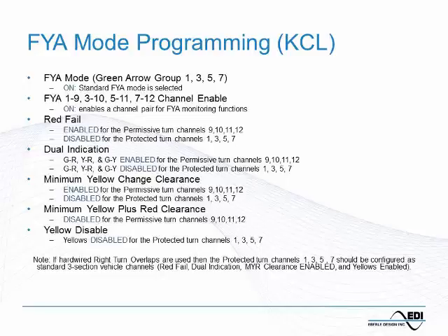So that's the flashing yellow arrow standard mode. Again, everything is 1-to-1. The controller drives channel 9 for the overlaps. When we want to do a flashing yellow arrow sequence, it would go from channel 9 red to channel 9, the green would be flashing, indicating the permissive left turn. We would clear it to the solid yellow of 9 and then return back to channel 9 red.